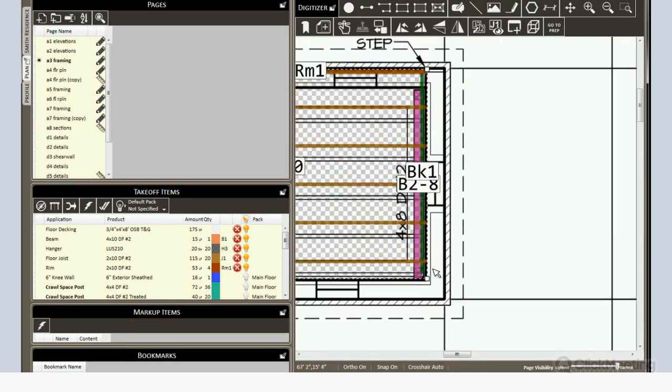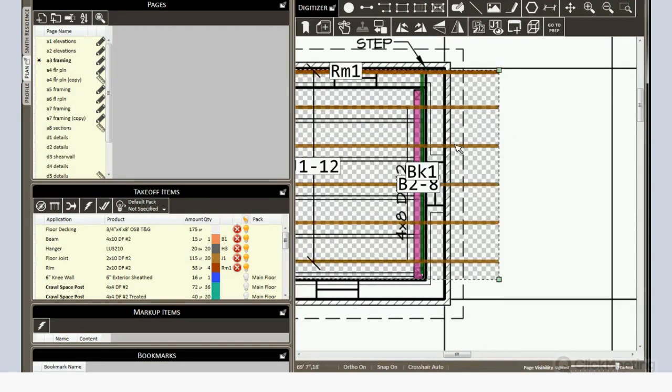If I selected this node and I wanted to shift this whole container out, again, I can select them, drag, hold Shift down, and now those nodes are moving in an ortho type fashion. Just drop them, and now that whole container shifts out in perfect orientation of flat horizontal on the page.